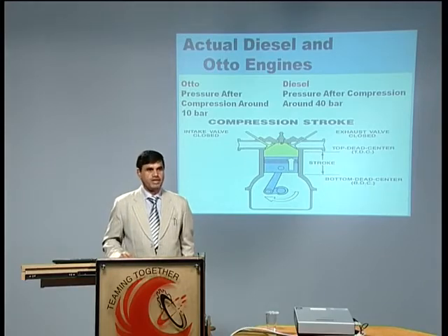But if I compare temperatures, in petrol engines the peak temperature during or after combustion is much higher as compared to diesel engines. The reason is the combustion duration, up to which the flame is propagating. I said in the case of a petrol engine it is around 40 degrees of crankshaft rotation, whereas in a diesel engine combustion can go up to 100 degrees of crankshaft rotation. Combustion is slow in diesel and fast in petrol. So the temperatures we receive in a petrol engine are significantly higher as compared to diesels.